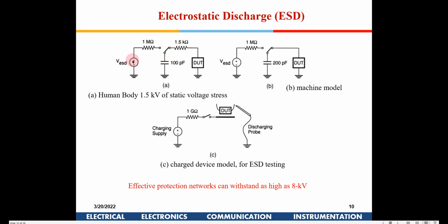So you have a VESD. Initially you charge this capacitance to the full voltage, and then you shift the switch here. Then you have to see whether there is any burnout in this circuit. So these kinds of simulations are done, and then the IO circuit is accordingly designed.